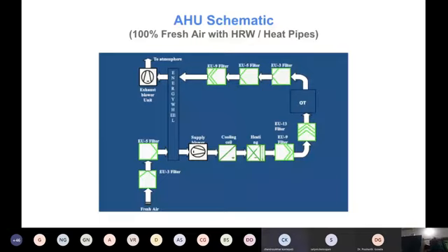Whatever air is picked from the operation theaters, ICUs or isolation areas, it takes out the energy enthalpy from the return air, and when it comes down at the bottom, the energy is transferred to the fresh air. So practically 70% of the energy can be conserved. So 30% will be the energy wasted.